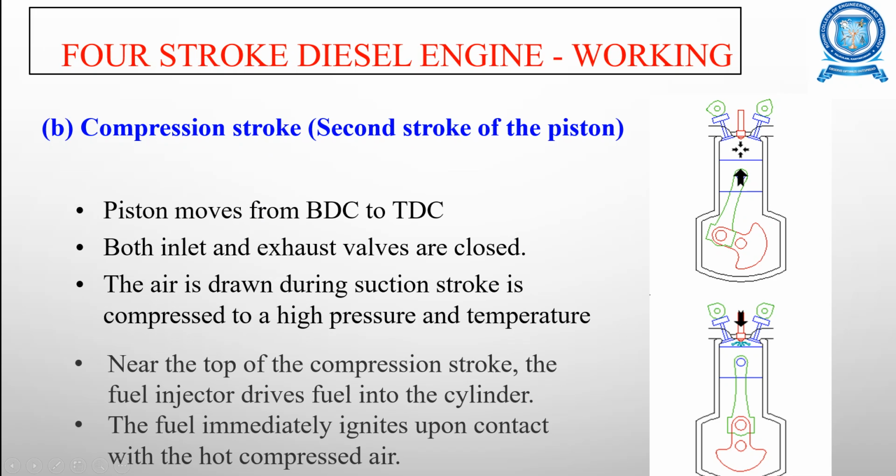Near the top of the compression stroke, that is when the piston is almost at the TDC, top dead center, the fuel injector drives fuel into the cylinder. The fuel immediately gets ignited upon coming in contact with this hot compressed air.